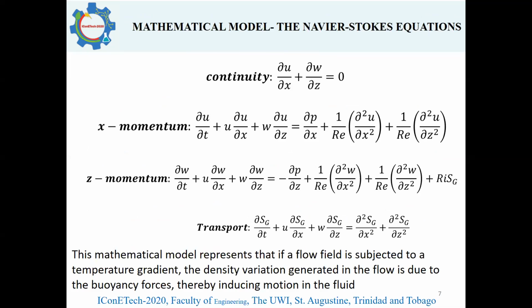I've derived the continuity equation, the x momentum, z momentum, and transport equations, as you would see on the screen. So this mathematical model now will represent a flow field that is subjected to a temperature gradient, a density variation generated in the flow due to the buoyancy forces, therefore inducing motion in the fluid.